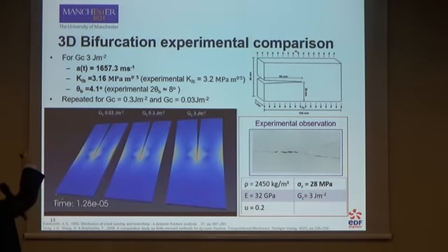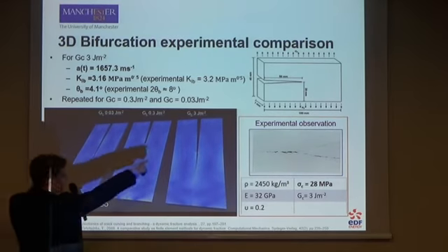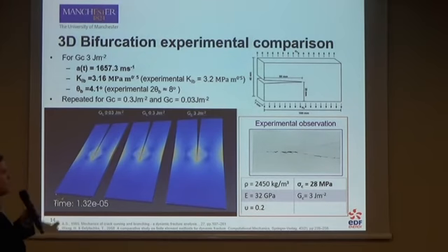We ascertain for the correct stress intensity factor that the appropriate angle is within 0.1 of the angle for the half branching angle, which is equivalent to what we see in the experiment. And this is for this crack here. If we iterate the solver over it more and more, we get a smoother crack shape, but for demonstration purposes, I made quite a coarse profile here.